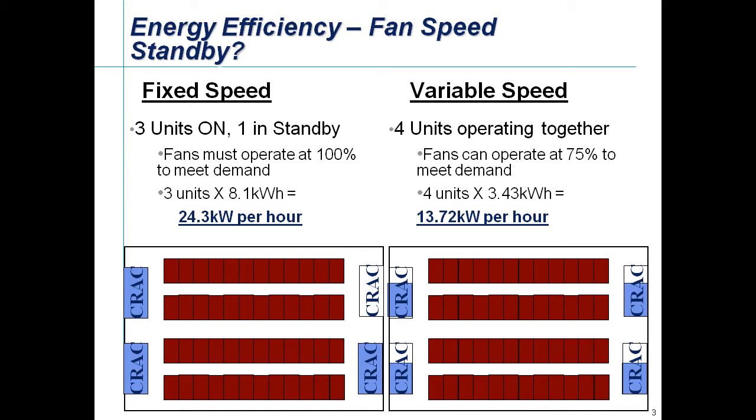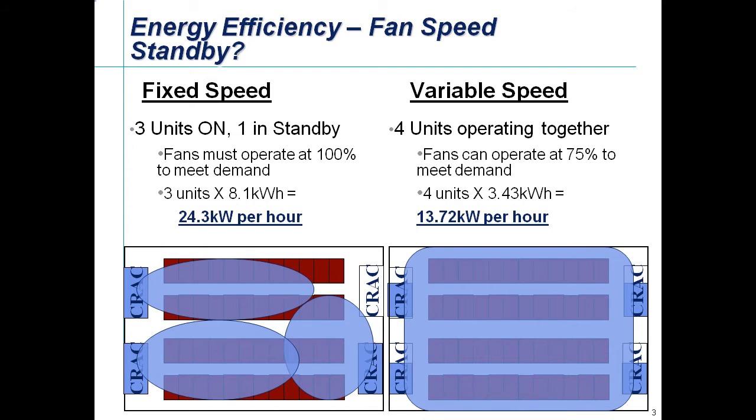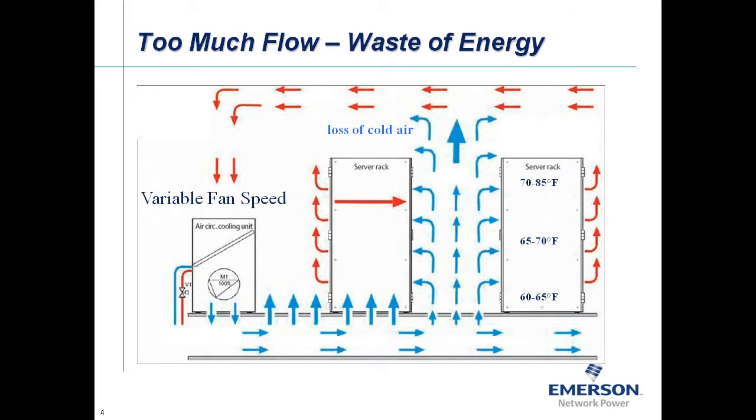In addition to the greater energy savings, the underfloor air distribution would be more consistent with the control strategy on the right. When a unit is placed into standby, as shown on the left, and the fan is deactivated, it creates a void under the floor that the other units will need to compensate for. Depending on the room and unit position, this could create a hot spot in the data center. Add in rotation and you have a real headache on your hands.